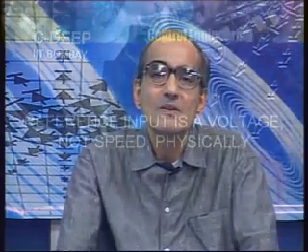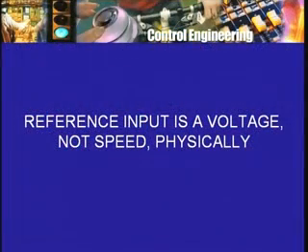The feedback signal was a voltage, because it is a field current which is to be adjusted or manipulated, and the field current will be manipulated by changing some voltage, because the voltage can be produced by an electronic amplifier. Therefore, we chose the reference input also as a voltage.